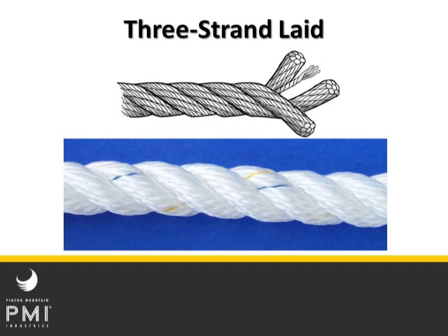The other thing with this rope is it twists. It gives you a lot of spin once you rappel it in free air. The cavers tried using three-strand ropes in these vertical pits around here in the southeast, which is one of the big reasons why we came up with trying to find another rope to rappel into, because you would rappel a 300-foot rope in free air and to the bottom of a pit where you don't touch the wall, and you get off the rope and pass out or throw up, depending on how well you handled motion sickness.